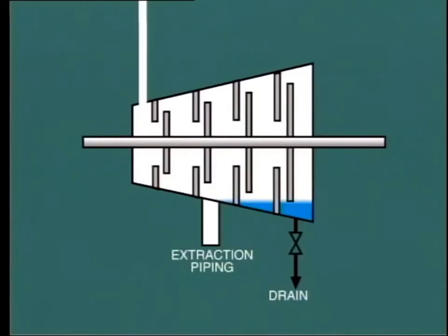We've been looking at the main features of a typical turbine startup and the precautions that must be observed. There are, in fact, many other precautions and observations that must be made during operation as well as during the startup of the unit. One very important area is the prevention of water ingress into the turbine.